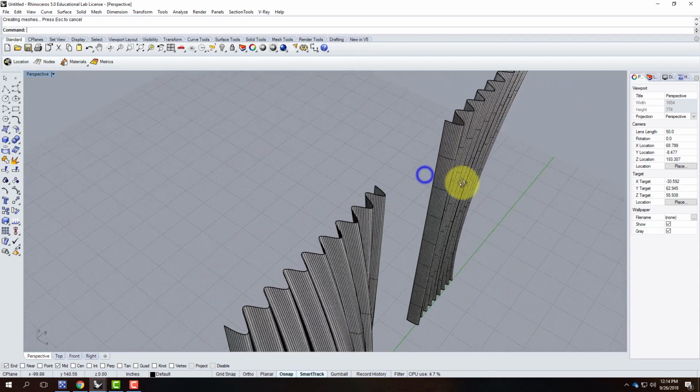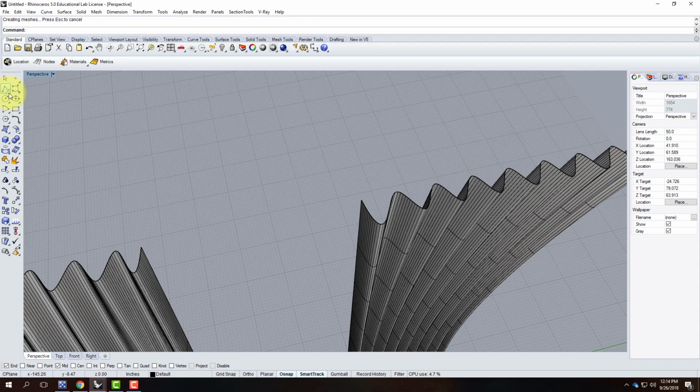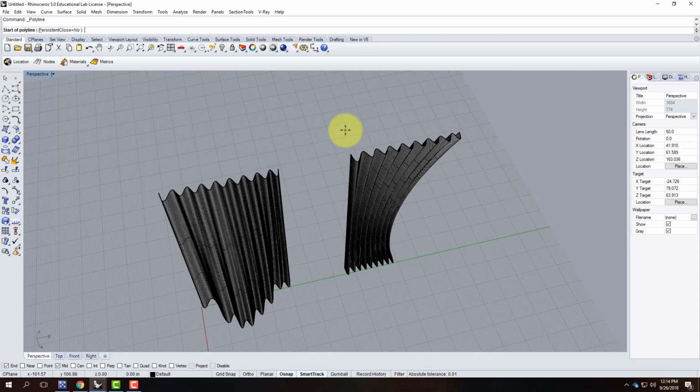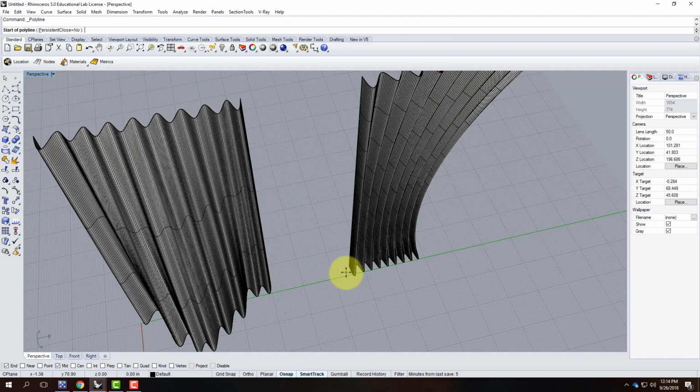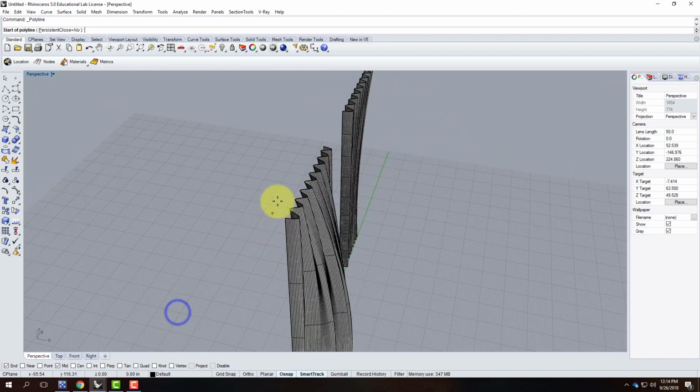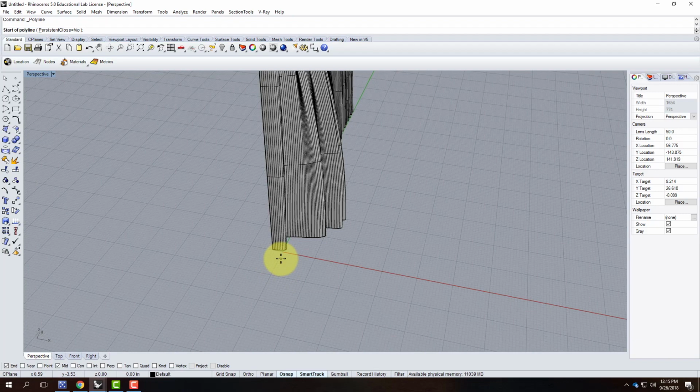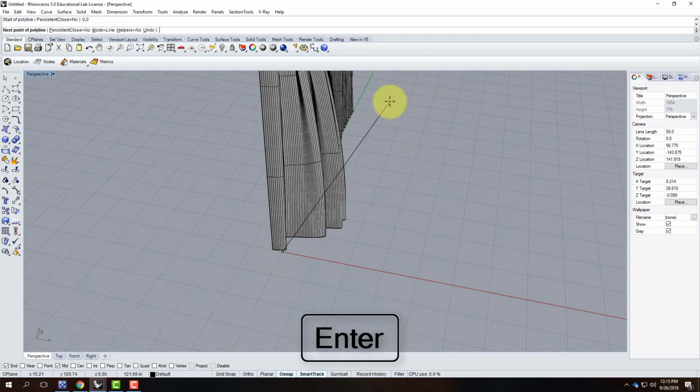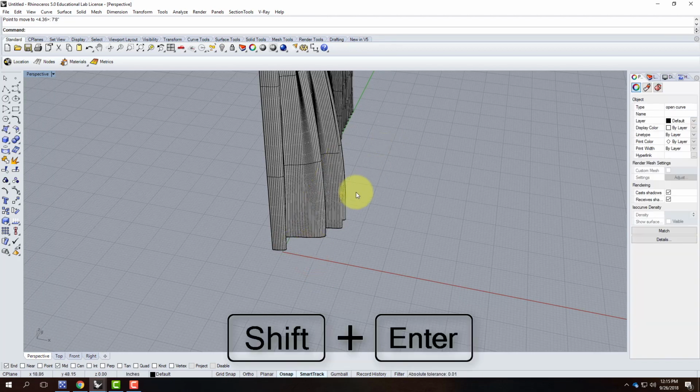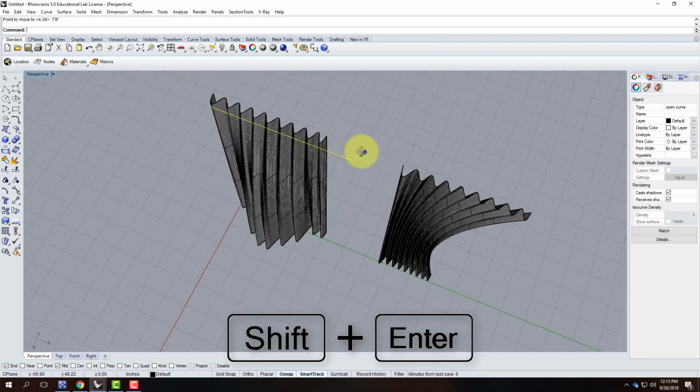The one last thing that I want to point out is, let's say that I needed a curtain rod. You always need a curtain rod too. We can use the same strategies that we've been doing to create a curtain rod through these. So I could start at 0, 0. And I said it was 4 feet long. So let's do 5 feet. There it is, right there. Let me move it vertically. Let's do 7. There we go. I'm trying to create where the rod would be.